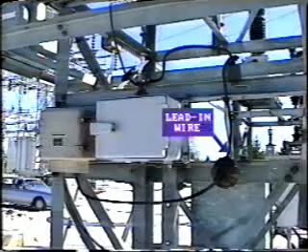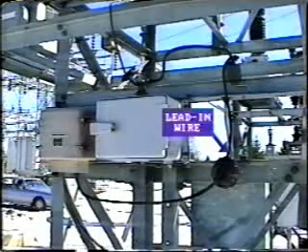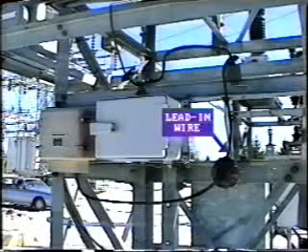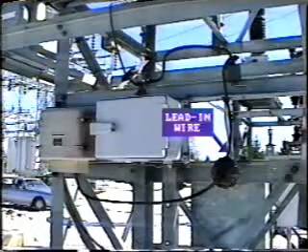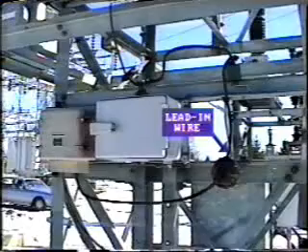Though this is normally a low-voltage connection, it could rise to line potential if the drain coil fails. The lead-in wire may be supported on insulators or run in PVC conduit. It may even be run in metallic conduit, but this is not good practice, as the capacitance of the wire to ground will be larger in metallic conduit, and this extra capacitance could affect the tuning action of the LMU.